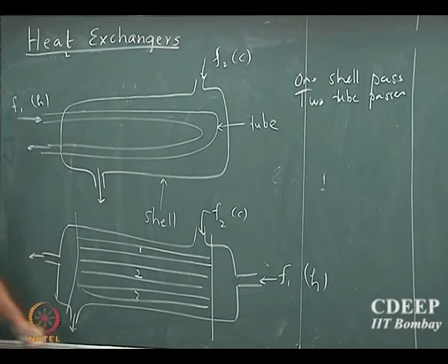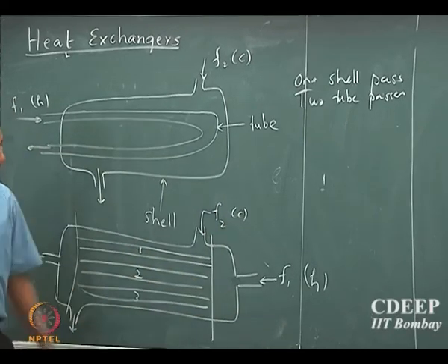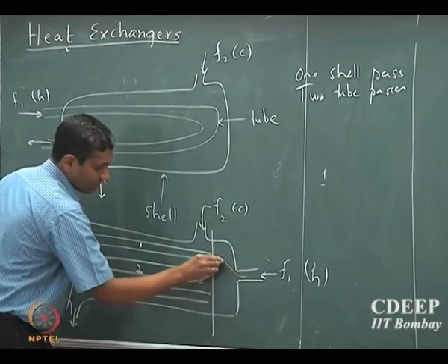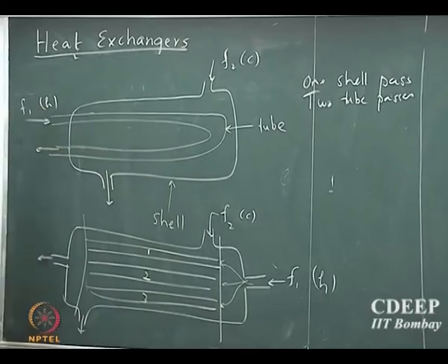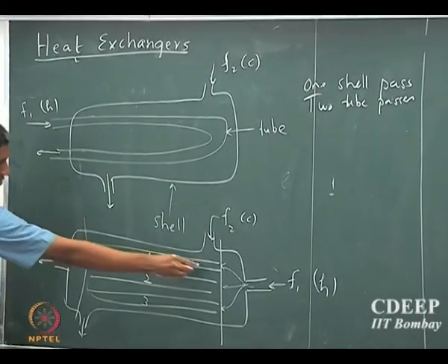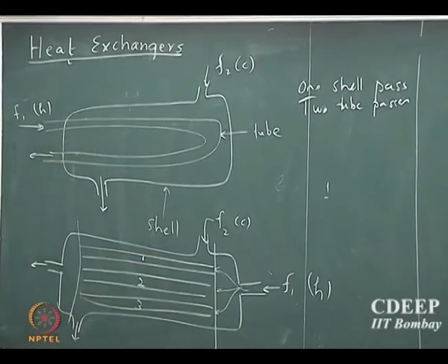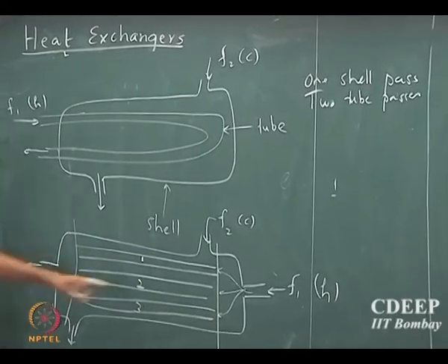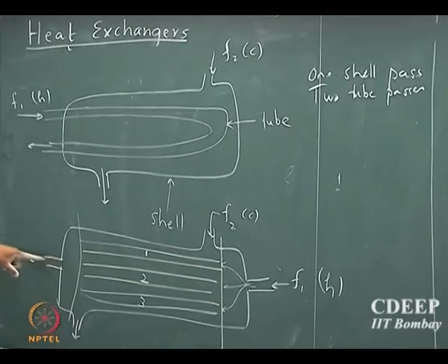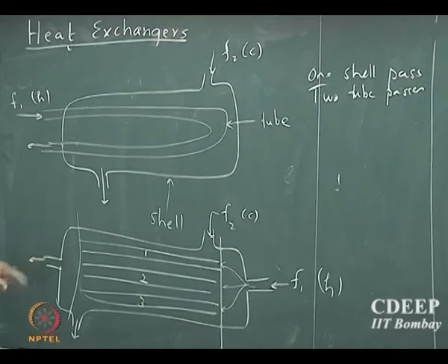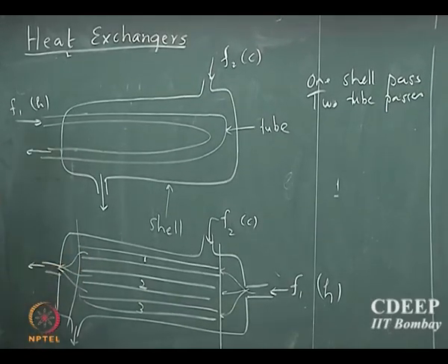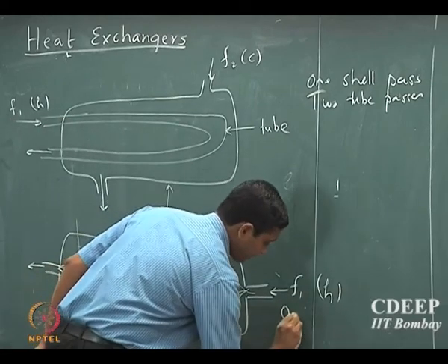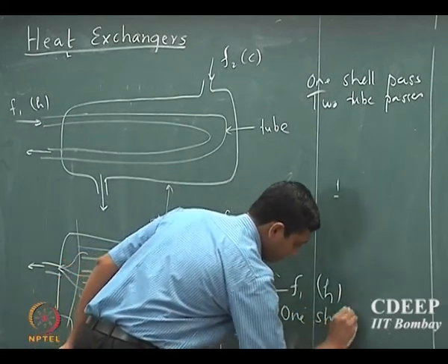So here the hot fluid which comes into the shell and tube heat exchanger gets distributed into these three channels, and then when they go through these tubes, they experience heat exchange only for one length scale of the shell. Okay. So then they go out together. So this is what is called one shell pass and one tube pass.